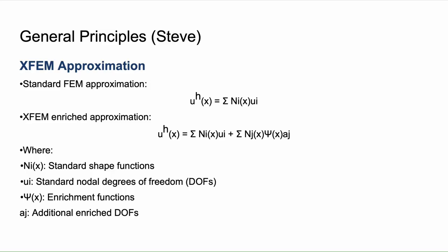And next part, let's look at how XFEM builds upon standard FEM approximation. In the standard FEM, we have this formula expression where the displacement field is approximated as the sum of shape functions multiplied by nodal displacement.